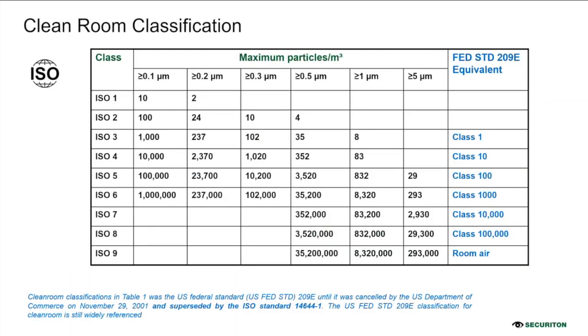With that information, as I mentioned about the clean rooms, the blue color here on your right indicates the older classifications or standards, which were used to classify class A up to class 100,000. So that is to understand how they're classified. The class indicates the level of particles equal to or greater than 0.5 micron per cubic meter, they will call it. And a clean room designed in these classes has to comply with certain things.